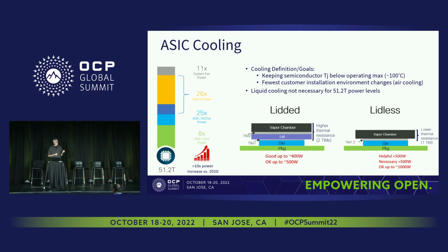And so typically those are not as conductive, right? You have a piece of copper that is like 300 watts per meter Kelvin. It's great at pushing heat around, but the thermal interface material, because it needs to be semi-liquid, will typically be some sort of paste with metal particulate in it. And so that'll be more on the order of 3 to 6 watts per meter Kelvin. So that's way less in terms of efficiency.